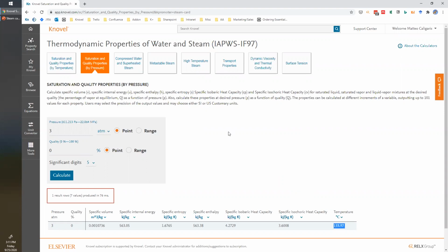meaning that I would have to turn on my cooling system at about 100. A bit earlier than that, maybe 120, to get started and decrease the temperature to prevent potentially an explosion or the activation of some safety device. And this is one example, right? And this is one way to use it. There are plenty of other properties that can be calculated.